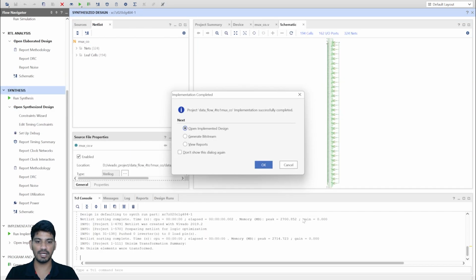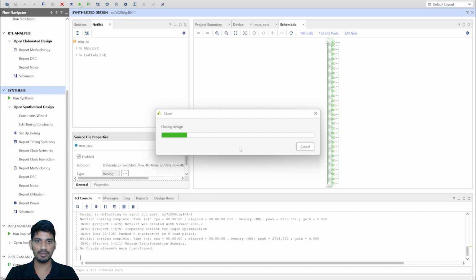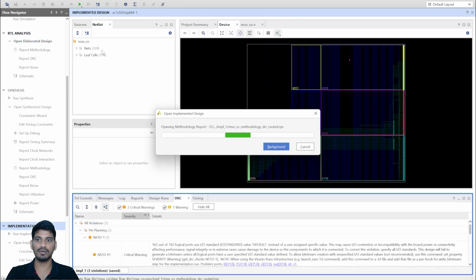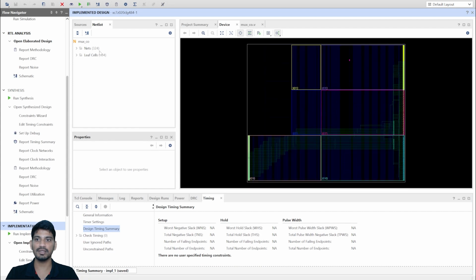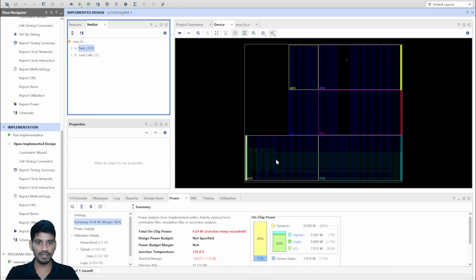For both synthesis and implementation. Let's see the implemented design of this conditional operation base. So how many nets is it consuming? It is consuming a total of 227 nets, but after implementation, it has gone up to 324 nets. Now you see the difference between these two designs. This design is very compact, which is only taking 107 nets, right? And it has routed from here to here.